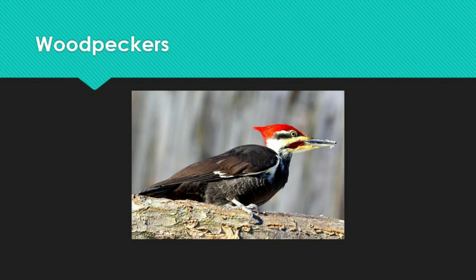Untreated wood can be exposed to moisture and spores from these woodpeckers, resulting in deterioration and a loss of pole strength. And if degradation or decay develops, it might lead to further attacks and the formation of a cavity. Woodpeckers frequently utilize the same holes for breeding in subsequent years. Small and medium-sized cavities do not cause major structural damage to the pole, but a higher number of them will. The main issue is that water entering the holes will promote fast fungal development, resulting in internal wood decay.